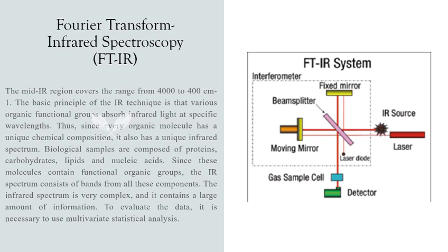A change in the characteristic pattern of the absorption bands clearly indicates a change in the composition of the material or the presence of contamination. If problems with the product are identified by visual inspection, the origin is typically determined by FTIR microanalysis. This technique is useful for analyzing the chemical composition of the smaller particles, typically 10 to 50 microns, as well as larger areas on the surface.